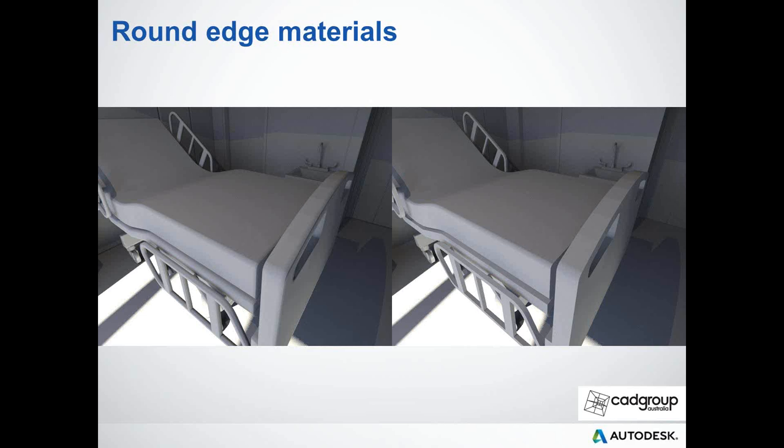So instead of chamfering or filleting your detailed models in the Revit environment and linking through to Max, there's a very powerful tool within 3ds Max Design where the materials create this effect in the visuals. And you can see this with the corner detail of this hospital bed.